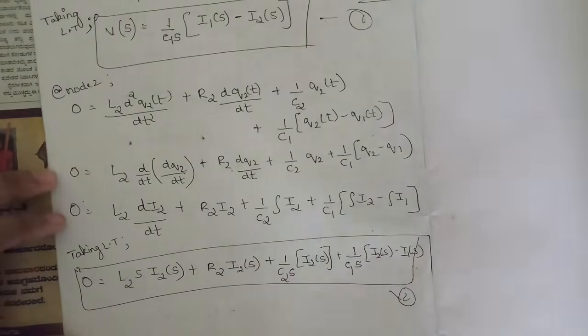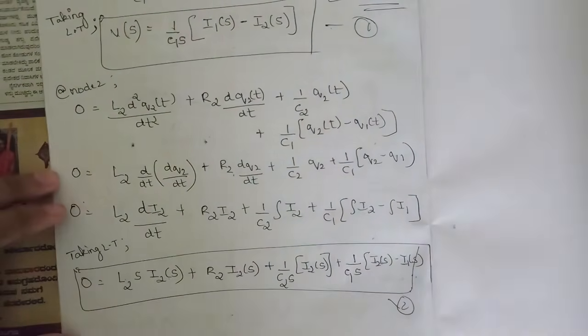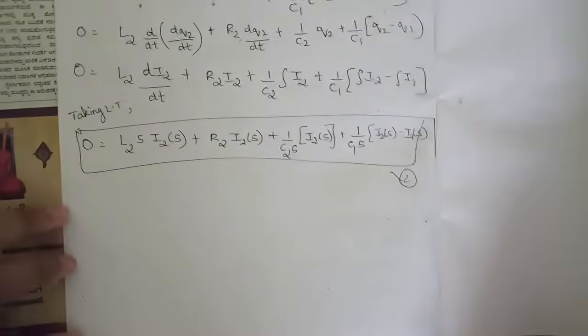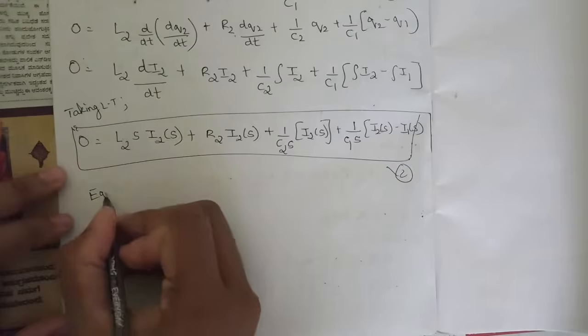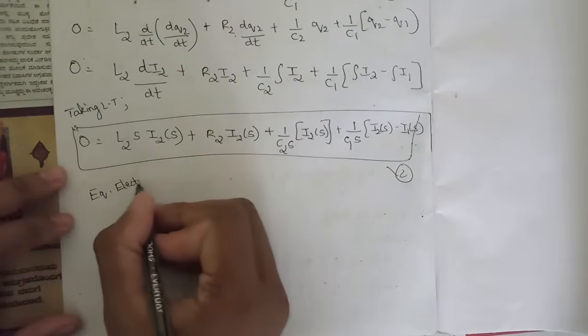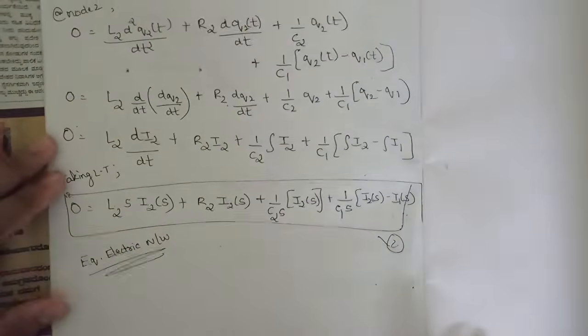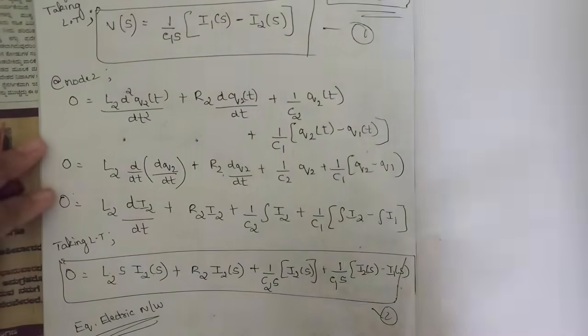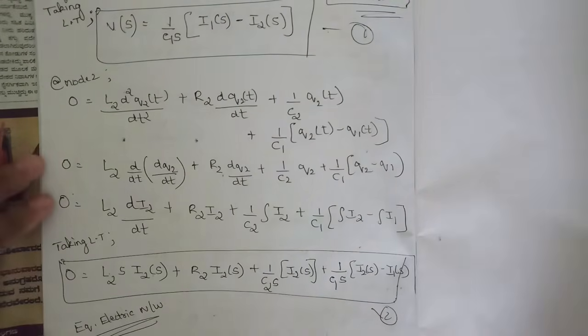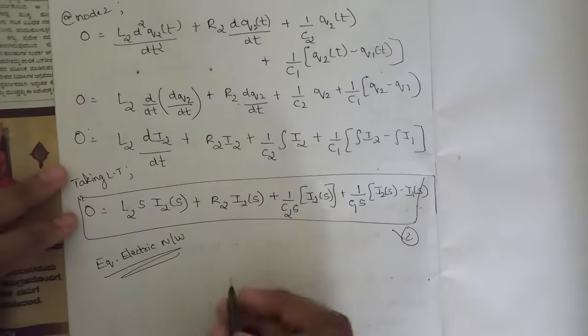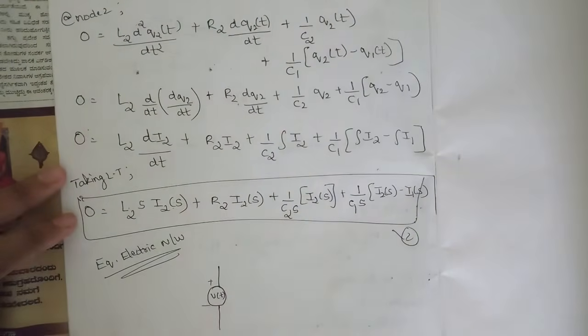So these are the two equations. By using these equations, we are going to build a circuit for FV analogy. That is, now we need to build the equivalent electrical network using equation 1 and equation 2, okay. Here we know that this is FV analogy. So first we need to write a voltage source around it, V of t, plus minus, okay.